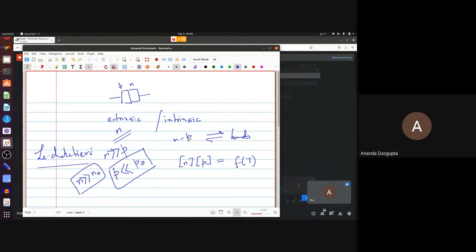The initial advantage which you had, because there were donor ions which were giving more electrons, is almost washed out. And the same happens on the p side. So basically what happens once the temperature rises a lot is that the junction between the p and the n, which is never really as sharp as we draw in the first place, simply gets washed away. And you end up with a single piece of semiconductor, not a junction, and then there's a sudden rush of current. Now, what might typically happen there is that your system may simply burn out, which is true. Even if it doesn't burn out, it will cease to function as a diode.